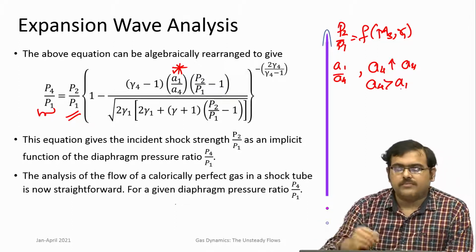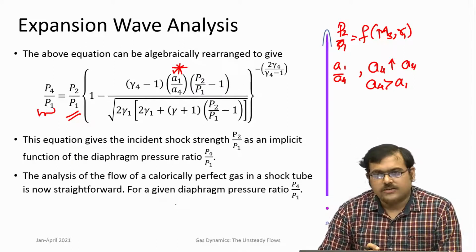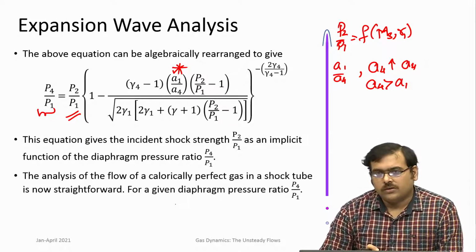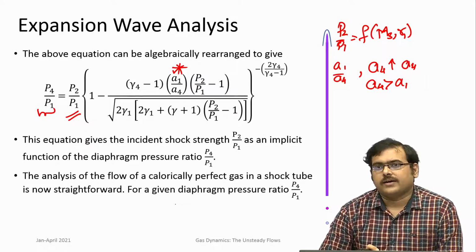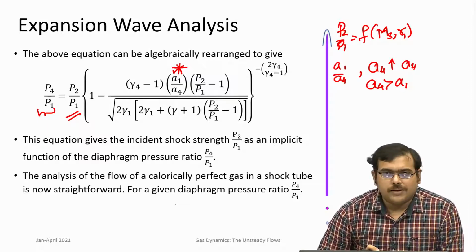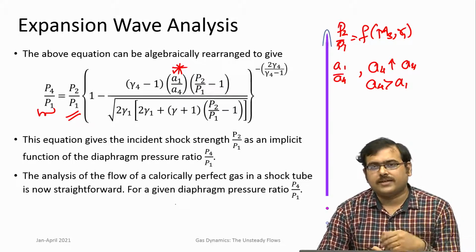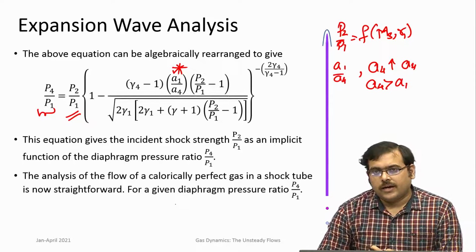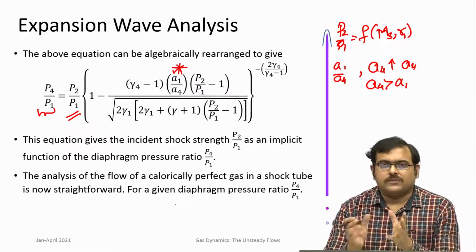And this is a guiding principle when we look at shock tube applications as well as experimentation. We always like to keep the driver side speed of sound higher than the driven side speed of sound, and this is accomplished by many means. You can get higher A4 by using a different, lighter gas, and usually helium is used to get stronger shock waves with the given pressure ratios.